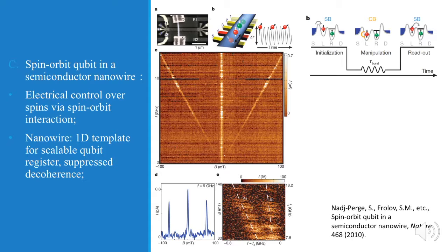In figure A, on the left side, it shows an image of our nanowire device. Two electrodes, source and drain, are used to apply a voltage bias across the nanowire. Voltages applied to 5 closely separated gates underneath the nanowire create a confinement potential for 2 electrons separated by a tunneling barrier. Similar to pure spin states, a magnetic field B controls the Zeeman splitting. The crucial difference is that in the spin-orbit qubit, the orbital part of the spin-orbit wave function is used for qubit manipulation.